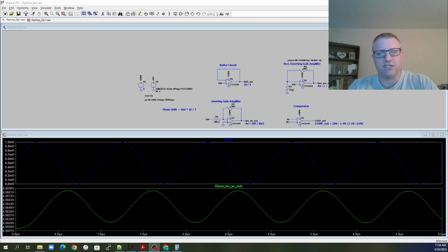So through these simulations, we've seen the op amp and these parameters and how they affect it. We've seen the VCM, right? We've seen that when it says 0 to 3.5 volts, if we try to go above that input voltage, our output does not reflect correctly because we've exceeded that VCM. We've also seen the output rail to rail. We've been able to see the rail go up to 5 volts so long as we stay true to that VCM and don't go above that.